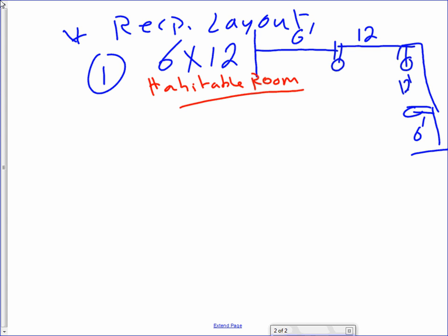Did you guys hear me? When you walk into a room, one receptacle in the center of a wall. From the get-go, easy. Grab a receptacle, snap to center in CAD, bam, we're done. Now we have 4 receptacles. Every room has 4 walls, 4 receptacles. Then you start measuring from this to the corner. Do I have more than 6 feet? Yes. Shift it slightly in. You start shifting it. Did you guys hear this trick? First you put them in the center, then you start adjusting them for this 6 by 12 rule. This rule applies to every habitable room: kitchen, dining room, living room, bedroom, any habitable room.